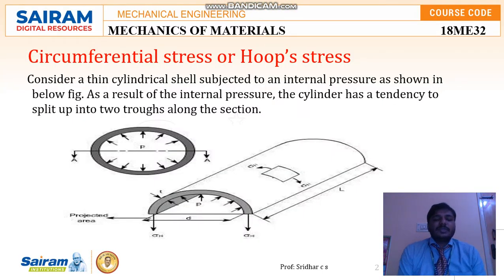Yes, the circumferential stress, what we call the hoop stress. In this diagram, we have taken a view of that particular cylinder. You can see two diagrams, which are views of how the pressure is distributed inside the cylinder along the x-axis and how it can be split up through these sectional views. We have only considered sectional views for this derivation of the circumferential stress, or hoop stress.